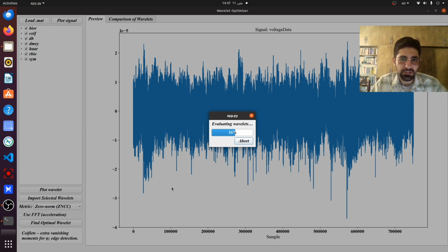The drawback is that wavelets with higher energy will have a higher score in this comparison. So it won't be a fair labeling, and we are not interested in such a metric for biosignal processing, especially for EEG, ECG, or even MEA. The next metric is the cosine metric.